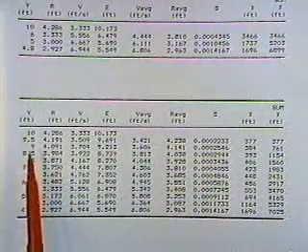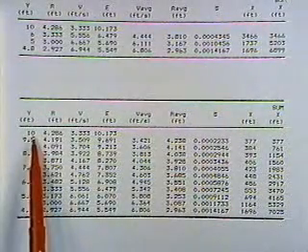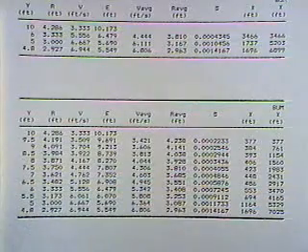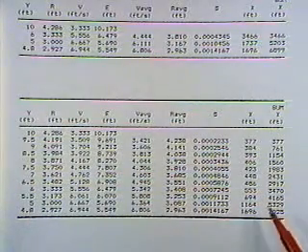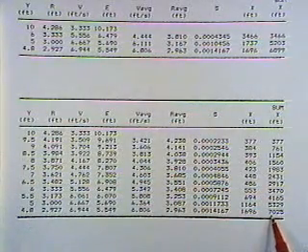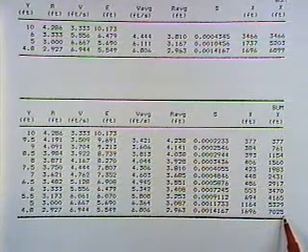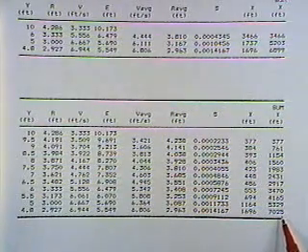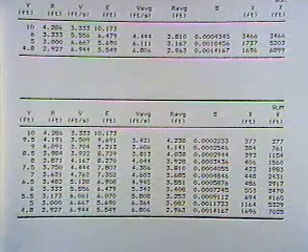When you run all the computations out from a 10 foot depth to a 4.8 foot depth at a 1/2 foot step size, the horizontal distance came out to 7,025 feet, which is pretty close to the 6,901 I got before. So basically, I'm not too sensitive to step size, as long as it's relatively small.